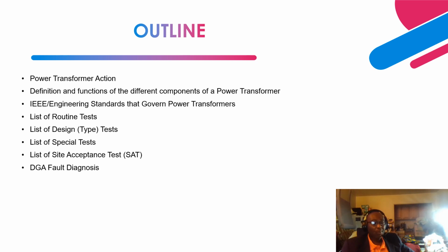This is when the transformer, after installation, is energized and is operating on no load. An oil sample is collected and sent to the lab where DGA and oil quality analysis is performed. And when you identify any severe condition of gassing, then that is when you have to diagnose the fault. And there are parameters and technologies out there that you utilize to diagnose the fault.